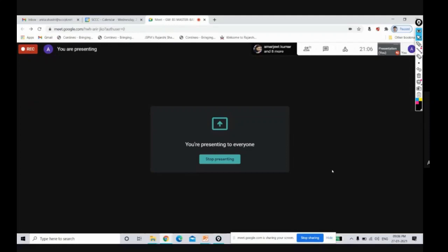Okay, sir. Sir, one small doubt is there. When we are designing the secondary beams in STAAD.Pro, if we are releasing the bending moment in the Z direction to release the torsion, then in practical site conditions, is it better practice to not provide the L length at that point, or simply put the straight bar over the main bar? What should be the process of detailing the reinforcement?